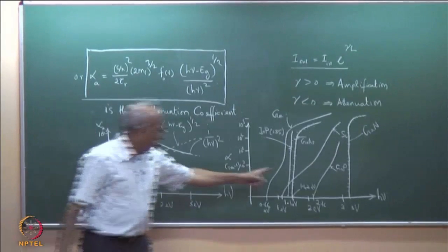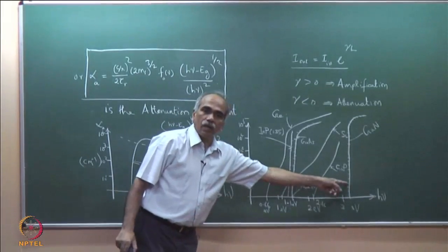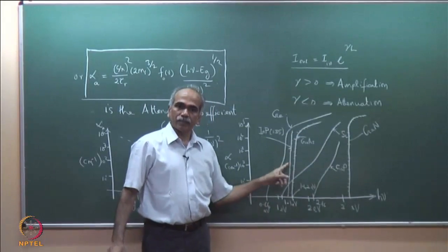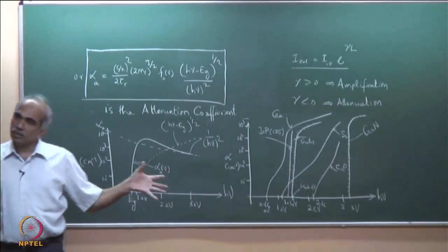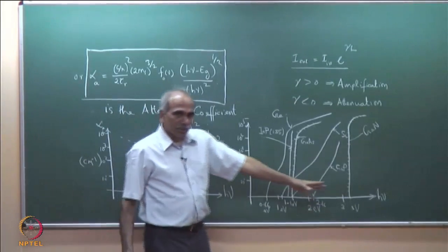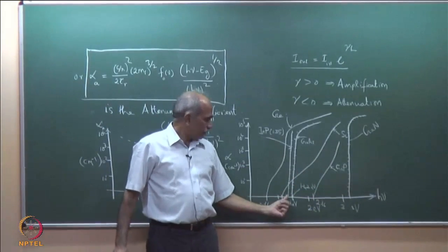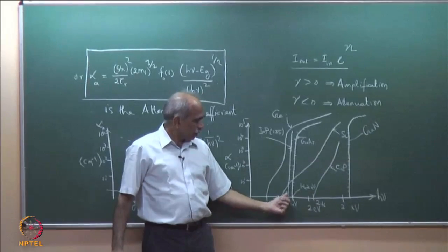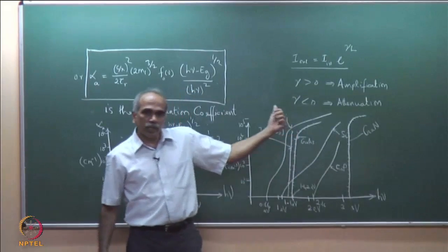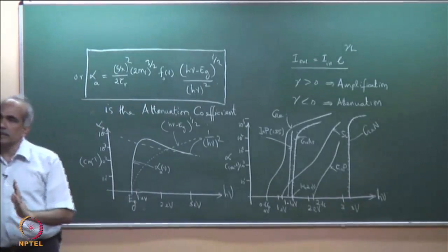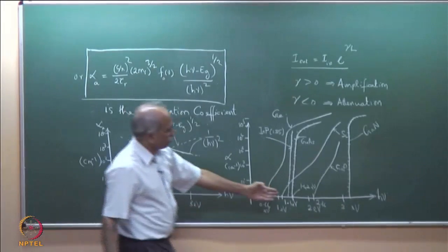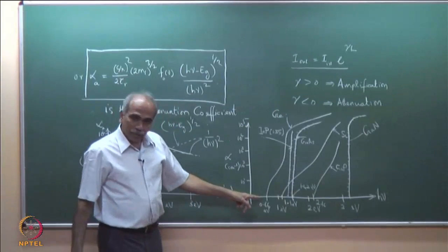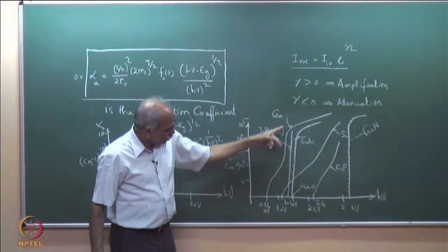If you just look at the graph, all the ones which are dash marked here are direct band gap materials and the other ones are indirect band gap materials. Just looking at the absorption spectrum, you can see that for direct band gap materials, the absorption curve shoots up almost vertically as soon as you cross Eg, whereas for indirect band gap materials, it goes like this.